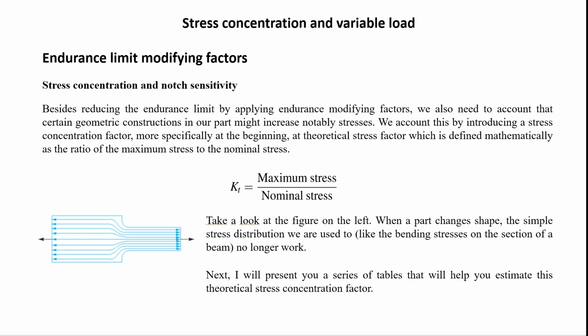Now, the stress concentration factor is defined as the relation between the maximum stress you're going to find and the nominal stress. But again, this is not something that you consider in the whole piece. Let's remember that when we talk about stresses, we started our subject by studying one specific point of a part, and we said that that point was going to have a state of stress represented by a stress cube.